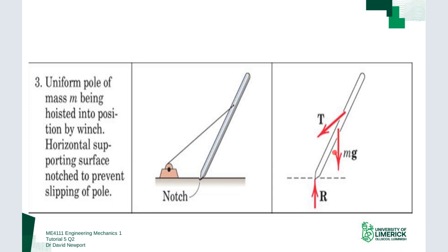Looking at my free body diagram, I've got my object in isolation. Instead of the cable, I have the tension T, so that's good. I have the weight of it, Mg, acting at the center of gravity. That's great. And when I come down here, I can see I've got a wall normal reaction force, which is fine.